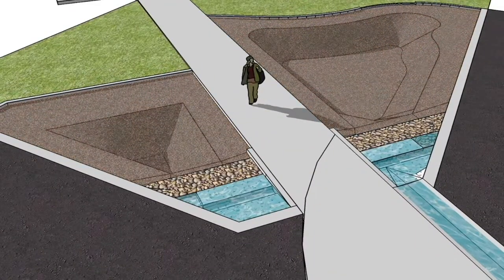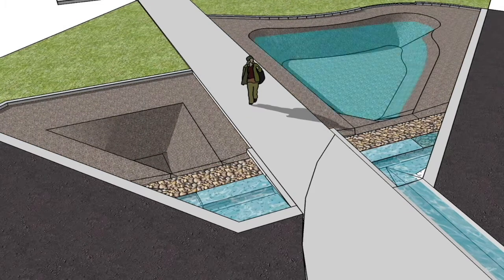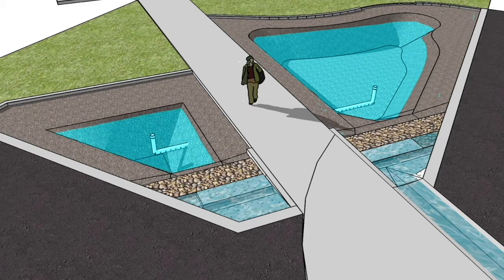This design consists of a surcharge zone underlain by a sand bed and underdrain system, which will allow for a greater depth of storage and will be effective at removing nutrients given a smaller available surface area. This design will also require less maintenance due to the limited vegetation.